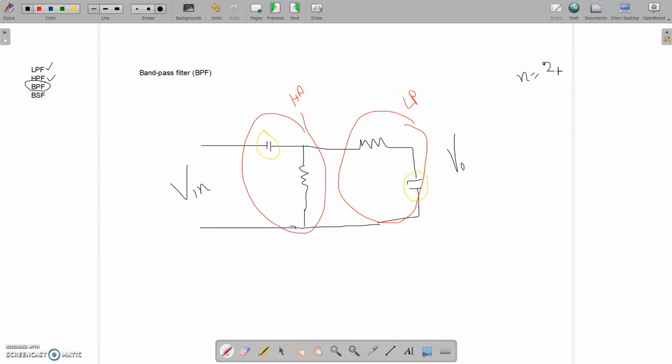So this is my band pass filter design. Now there is still the same issue that was with the low pass filter or high pass filter. The first issue is that the cutoff is a gradual cutoff. We can make it n equals 2, we can make it 4 or 6, higher order filters, to get a straight cutoff. We call it a sharp cutoff.